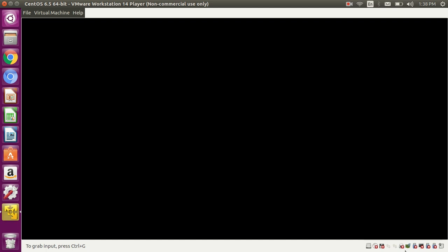That means whenever it is level 1 it will take all the inputs. Suppose our data is changing here. The clock input is this and the enable input is this. Then what will be the output of the latch? For this time, whatever is there, it will give this output. That means it will give some junk output, a small glitch. And at this glitch, the clock is also high and this is also high. What will the AND gate do? It will just propagate that glitch. Still, it will not serve our requirements.